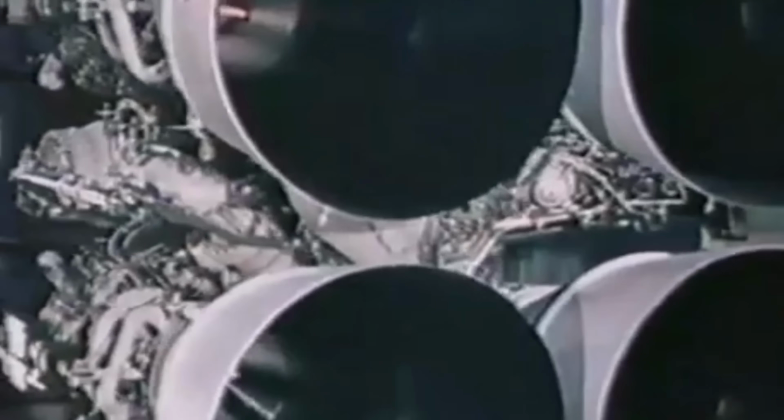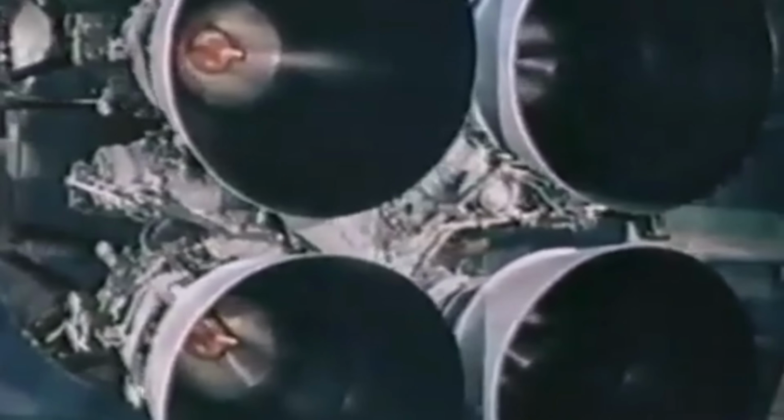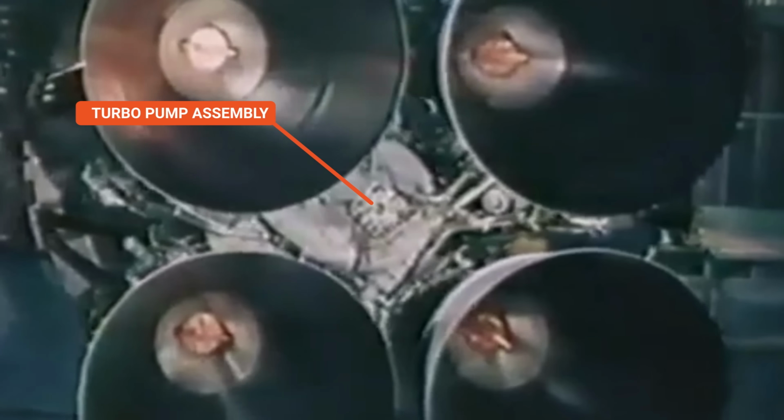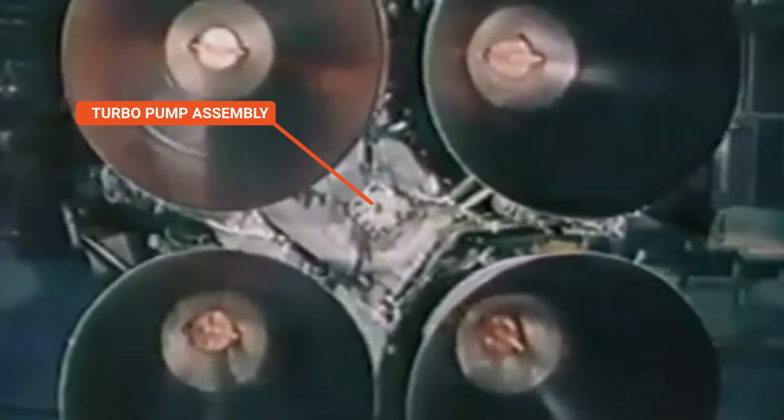But even with super lightweight composite tanks and the most energy dense and efficient batteries, there's a limit to how big you can scale up the system. Pumps can require thousands of horsepower. In fact, the RD-170's pumps require 170 megawatts of power, or 230,000 horsepower. Imagine having an electric motor that big.